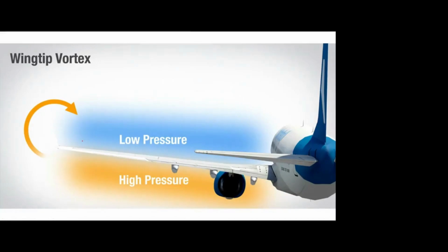Next one is winglets. Winglets, you know, right? Yes, sir. Okay. So here, assume this is the wing tip. There are no winglets. So on the upper surface we have low pressure, on the lower surface we have high pressure. Due to that, as I said, there is a side leakage flow. And this is what causes the wingtip vortices.